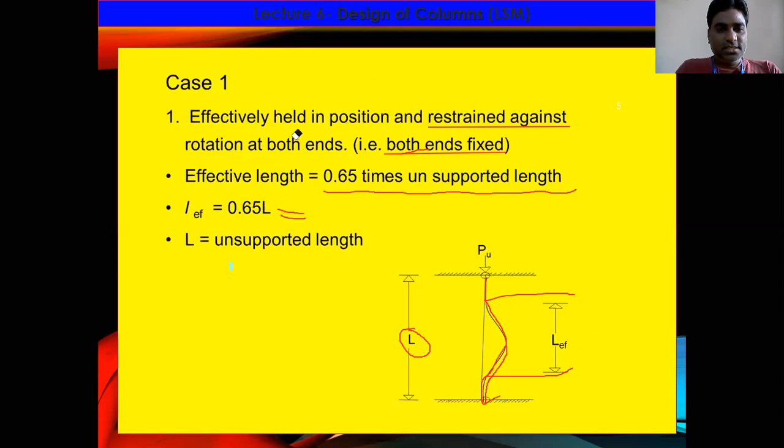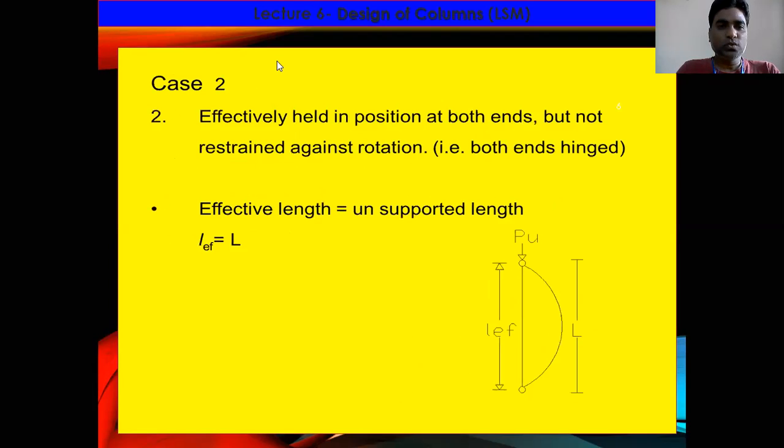The next case is case 2, that is, the supports are effectively held in position at both ends, but not restrained against rotation. That means both ends are hinged.